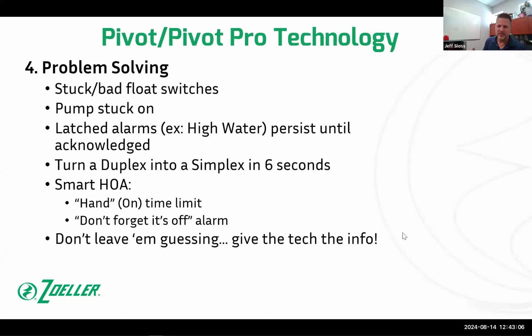It's going to give you fits because it's going to start reacting to that. If you lift switch 2 before switch 1, that's illogical, and the panel is going to make a big racket, because everybody's used to being able to do that. I'm going to lift one float at a time and just make sure that my inputs are working. You can't do that with this. Well, you can, but you're going to get alarms. So just something to think about.